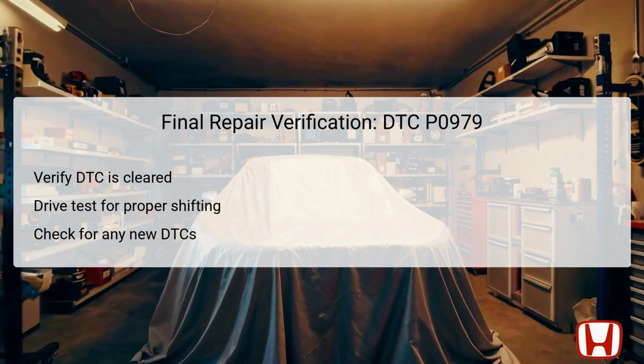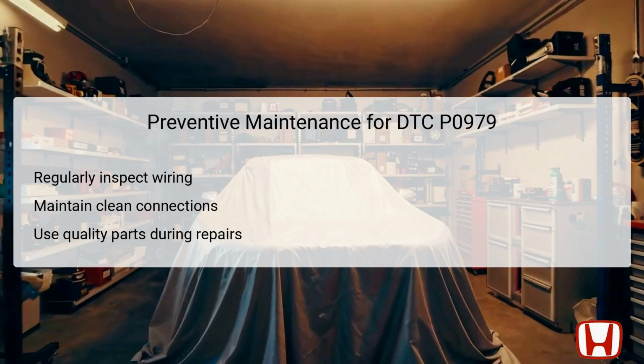efficiently and safely. To prevent the recurrence of DTC P0979, it is vital to implement preventative maintenance measures focused on the electrical components associated with the Shift Solenoid Valve C. Regular inspections of the vehicle's wiring can help identify potential damage or wear before it becomes a more significant issue. Ensure that all electrical connections remain clean and tightly secured to minimize the risk of electrical faults.